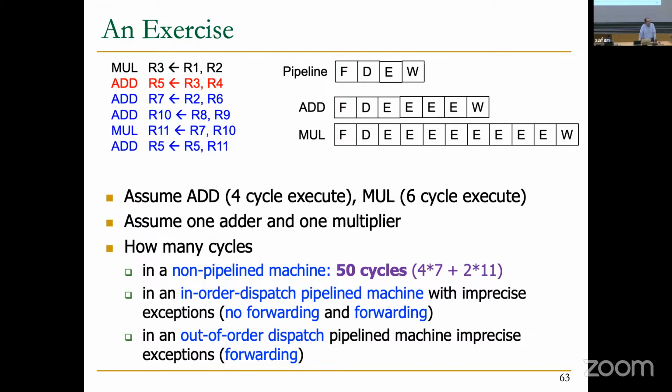Can you maybe tell a bit about where exactly the common data bus comes in? Where is it connected to? So we talked about broadcasting, right? We said that when the instruction is done with the execution, it needs to broadcast the value to the register file and reorder buffer, things like that, right? So for broadcasting, which means sending to everyone, we have a common bus.